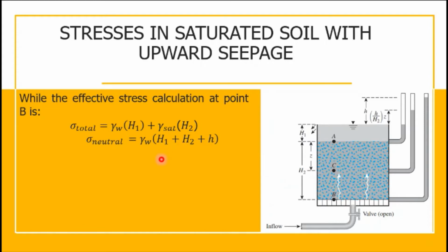And the neutral stress is equal to the unit weight of water multiplied by H sub 1 plus H sub 2 plus H, which is due to seepage.